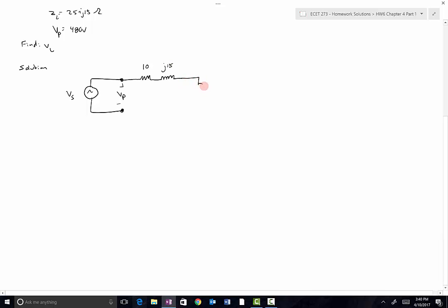Then what we do is we throw in an ideal transformer, plus minus, and a lot of times we call this VP prime right there. There's the primary side of the circuit. So everything from here over actually represents the transformer. Since this is a series circuit, IP flowing out of the source voltage is the same as the current flowing through the primary side of the ideal transformer.